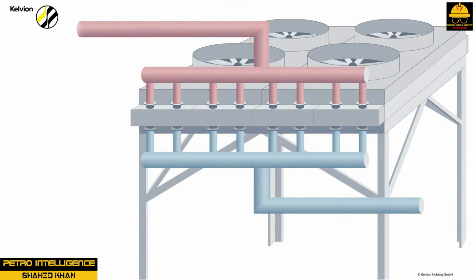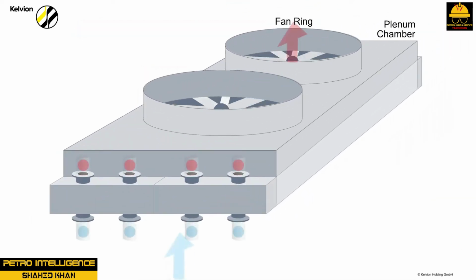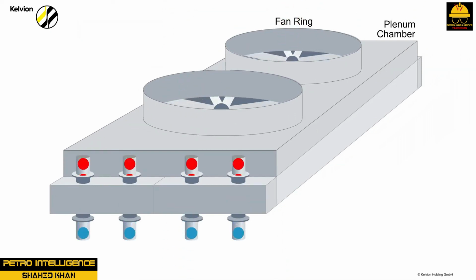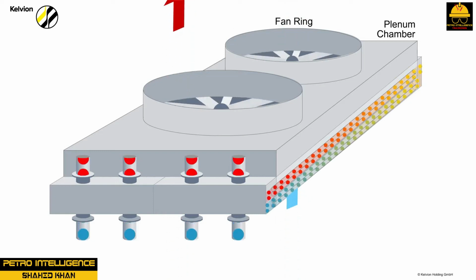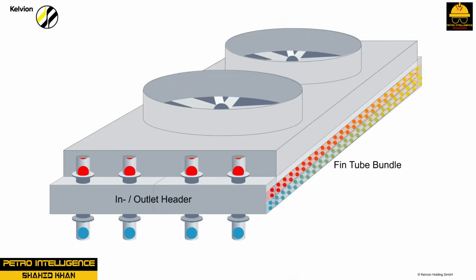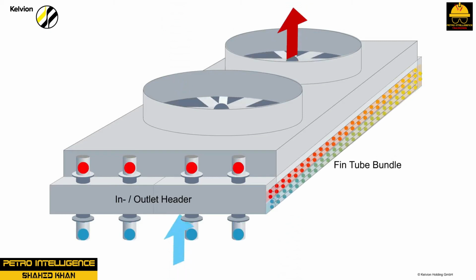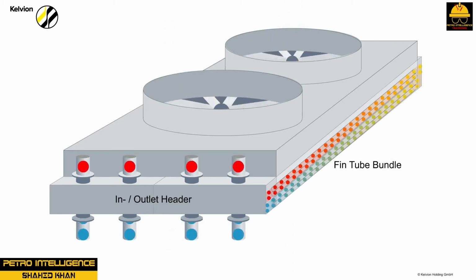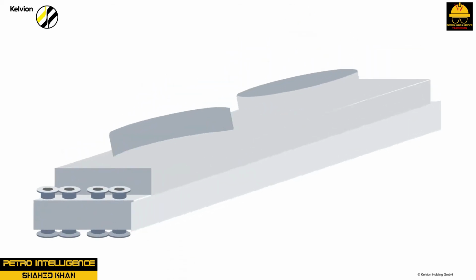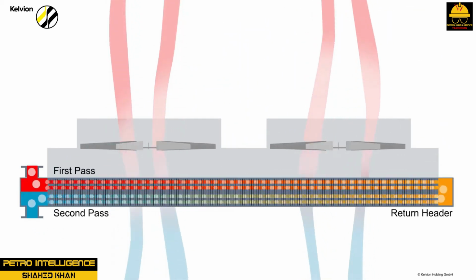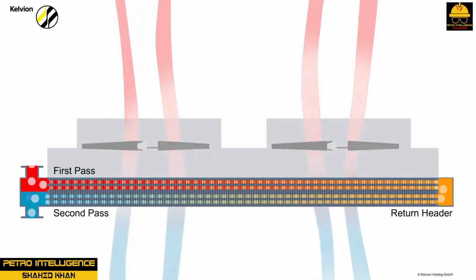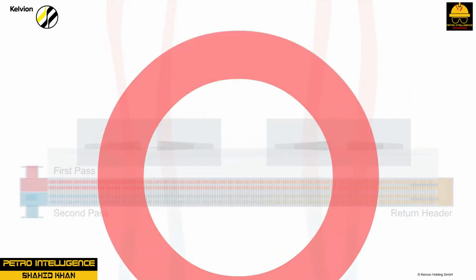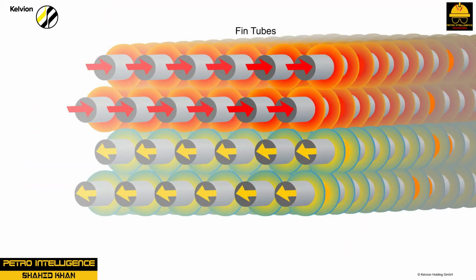The headers on an air-cooled heat exchanger can be classified as cast box, welded box, cover plate, or manifold. Cast box and welded box types have plugs on the end plate for each tube. This design provides access for cleaning individual tubes, plugging them if a leak is found, and re-rolling to tighten tube joints. Cover plate designs provide easy access to all of the tubes. A gasket is used between the cover plate and head. The manifold type is designed for high-pressure applications. Mechanical fans use a variety of drivers.